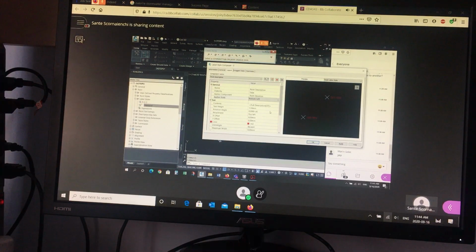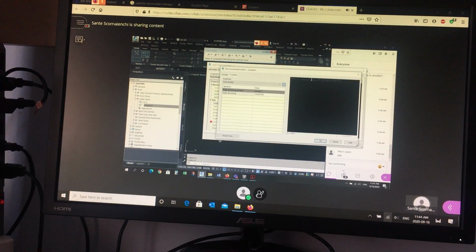The next thing you'll want to do, and we'll do this later, is if you want to change the decimal place accuracy, you have to go to the point number. You can go to the contents. See where it says text contents? In here, there's a set of instructions. In order to get access to it, you have to hover over here, click once, and then this little button shows up. If you click that, you get the menu. And then if you click here, this is the programming string.